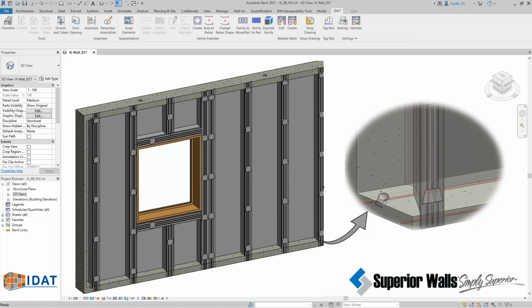Like here, this is a wall, thermally isolated wall, and isolated from the exterior elements. This is a foundation wall. It's monolithically poured with high strength concrete for giving it structural integrity, and of course it's reinforced with steel rebar, but also with polypropylene fibers. And this is typically used for basements or wood-based superstructures.